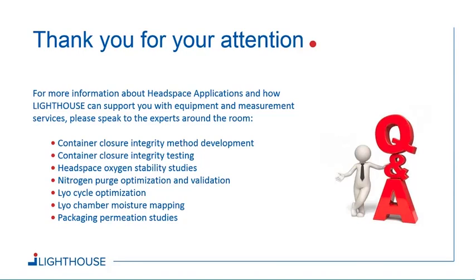They are talking about micron, submicron like leaks, and microbial and dye ingress will not be able to do that. So if you really follow the letter of the law in USP 1207, then you need to use one of these new analytical methods or deterministic methods. In the USP chapter, they mention helium leak test and Headspace as the two methods having the sensitivity capability of detecting submicron leaks.